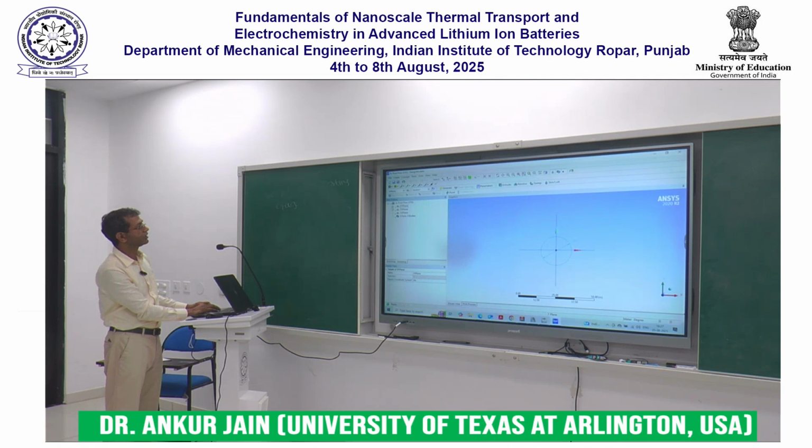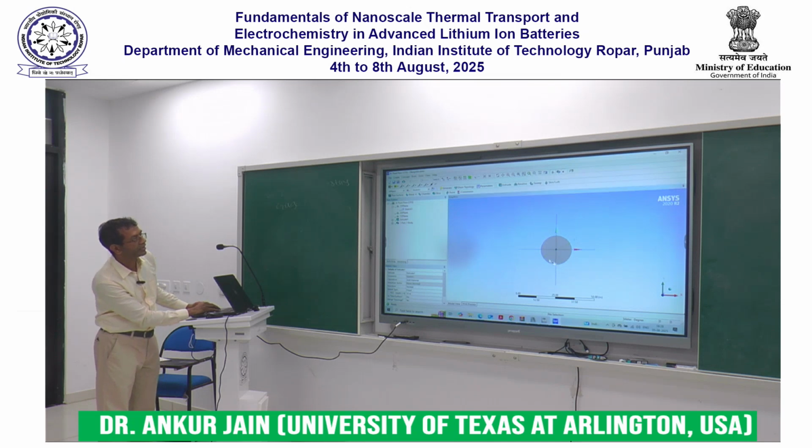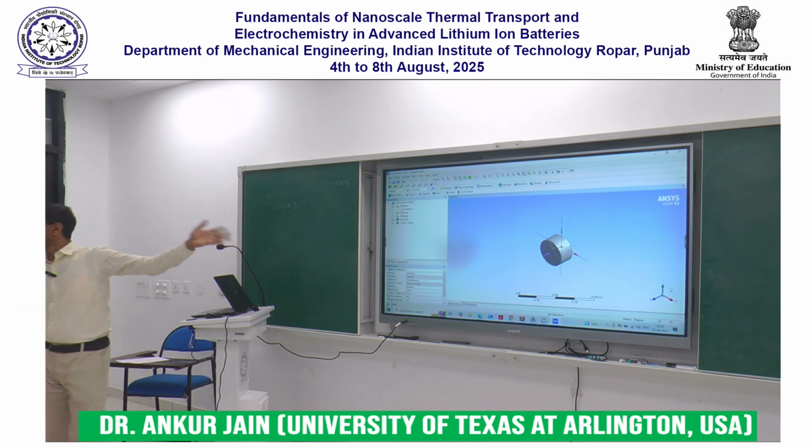Then I can go here and say create, extrude. I can select my sketch and I can say please extrude it to 10 meters. And when I say generate, it would have created this cylinder for me. So this is how my cylinder looks.